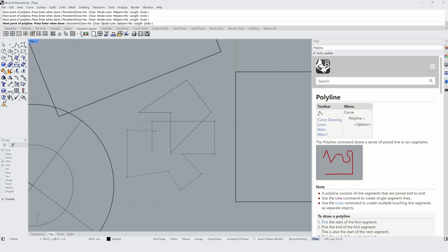So if I want to, let's say, have an ortho here, I can hold Shift, and now I just click Tab, and you can see it's kind of changed. So the white line has become the horizontal line. I've let go of both keys now, but it's locked into this horizontal orientation. By the way, hitting Tab a second time will lock the distance. So now it's a set distance, but I can put it at any angle, and hitting Tab a third time will release all of those locks.